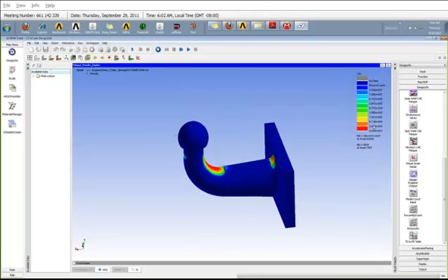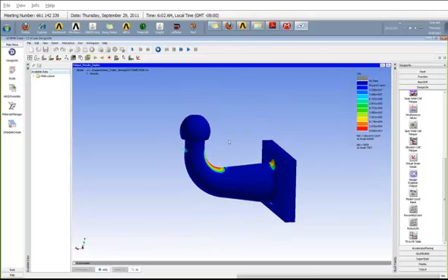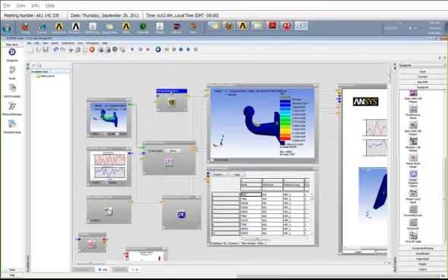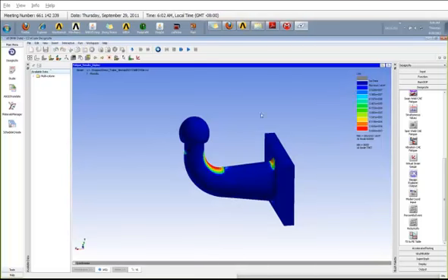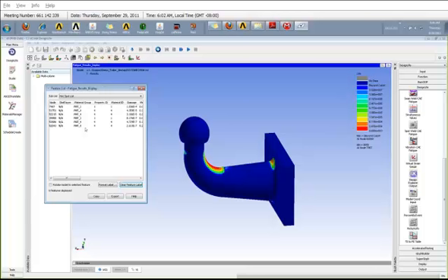So it shows that this part can be subjected to almost 10,000 cycles of that time history. It's slightly smaller because we used a scale factor of 10. And also, it calculates something called hotspot detection. Hotspot detection goes over the contour plots of these results and lists the critical regions. It does not list the top 10 critical regions or top 10 damage regions. It is mostly displaying the top 10 localized damage regions.